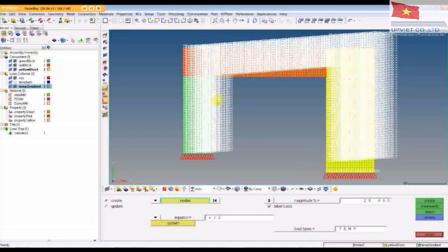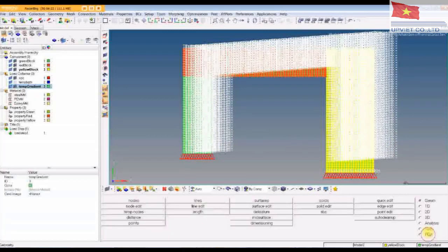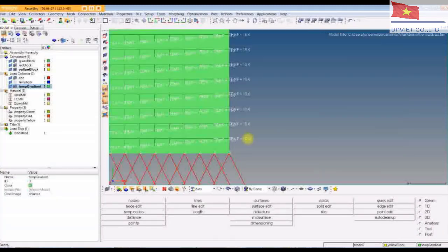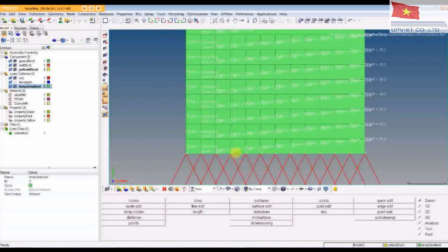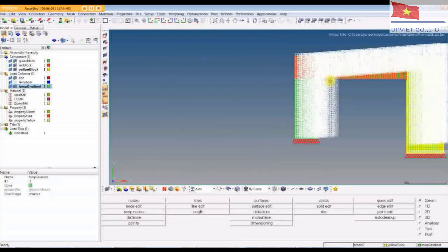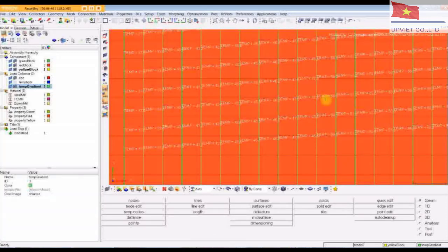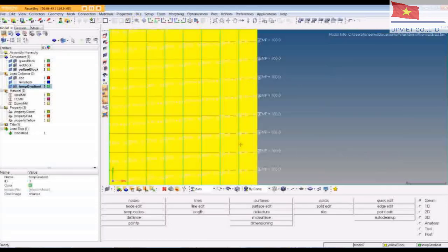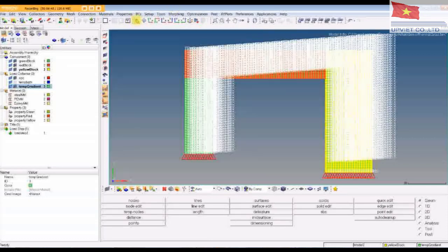And there they are. You can see where they increase because the magnitude of the arrows is a percentage. So very small over here, very large over here. So if we go and look at these, okay, we got 0 there, and each of these is increasing slightly, so we got 15 degrees on that leg. Over in the middle of the part, we're at 50. And at the end of the part, we're at 100 degrees, just like we want. So that is a temperature gradient.